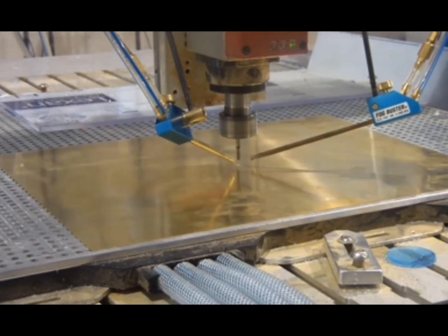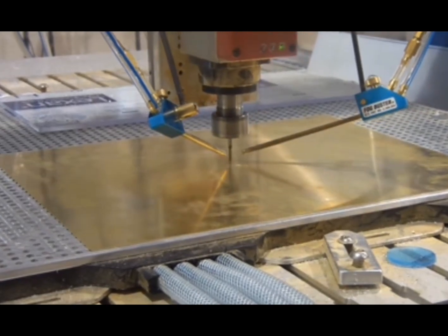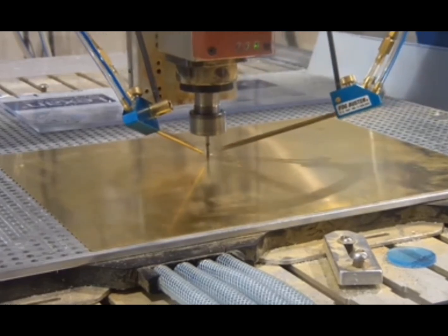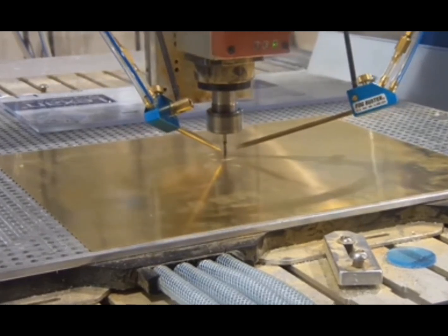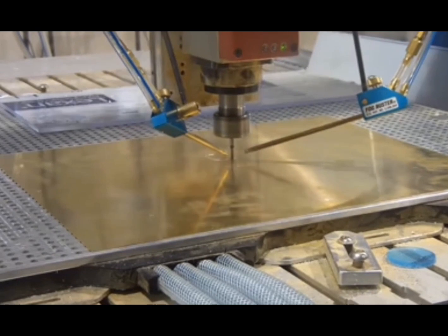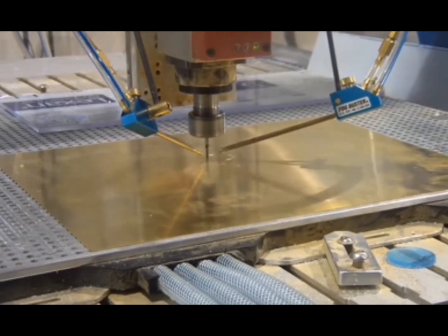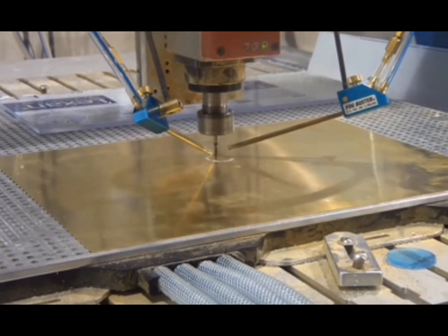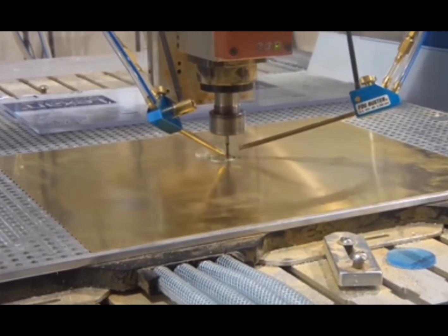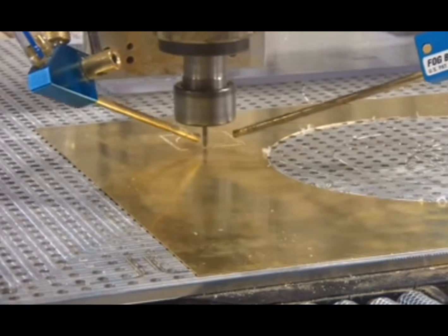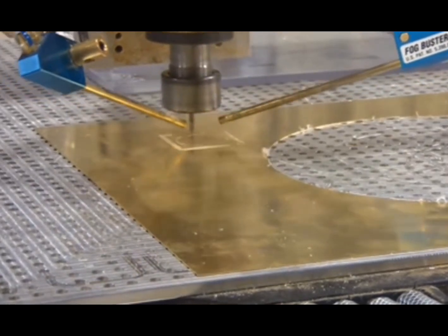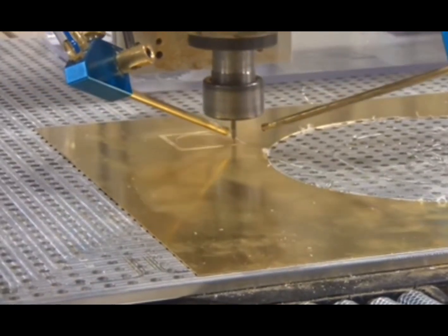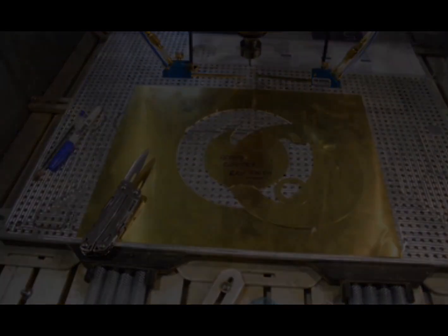10. Aluminum and brass machining. Working with non-ferrous metals like aluminum and brass requires increased cutting capability from your CNC machine, in addition to a little more attention and preparation. But when done properly, it can save time and money in the shop while producing a superior result. Determining and utilizing the proper feed rate and spindle RPM becomes more important when working with aluminum or brass, as they interact a bit differently with the blade than other materials.